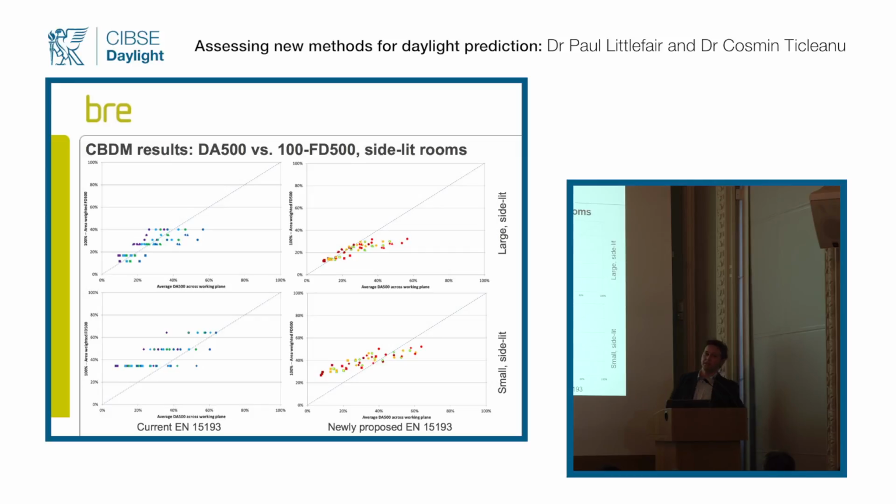That's the daylight dependency factor given by the European standard for 500 lux maintained illuminance. The reason why we used 1 minus that value, or 100% minus that value expressed as a percentage, was purely to have a similar trend in both parameters, because obviously daylight dependency factor and DA are inversely proportional. That's why we use that formula.